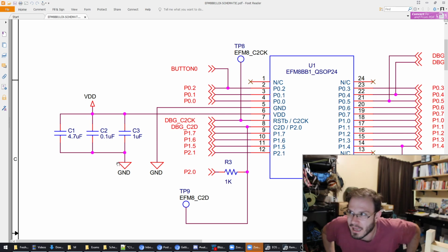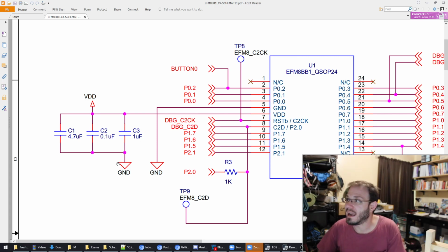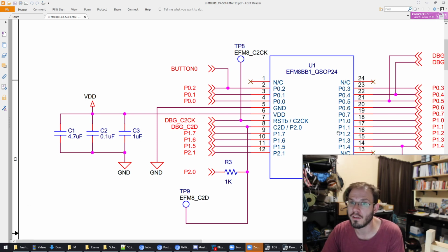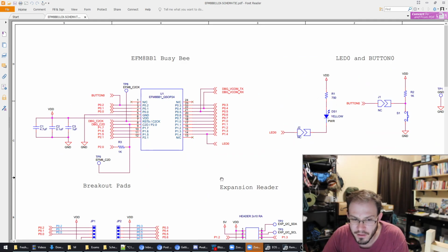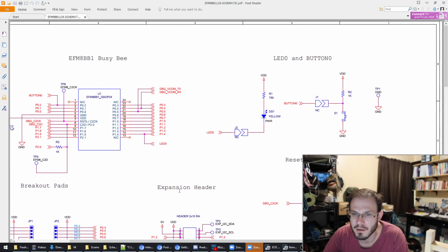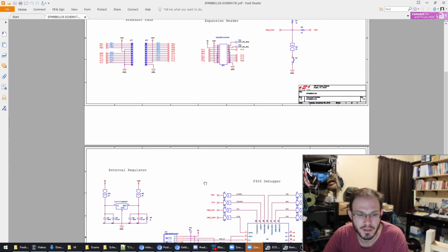So when I do a design, I go ahead and I design from a functional point of view, and then I go over the schematic looking for little problem areas. One of the passes that I do when I'm verifying a design before I get it produced is I go and look at all of the power signals, and I make sure that I have some bypass / decoupling caps in on all of my digital devices. So if we have any other digital parts on this board, we would have some bypass caps there too.